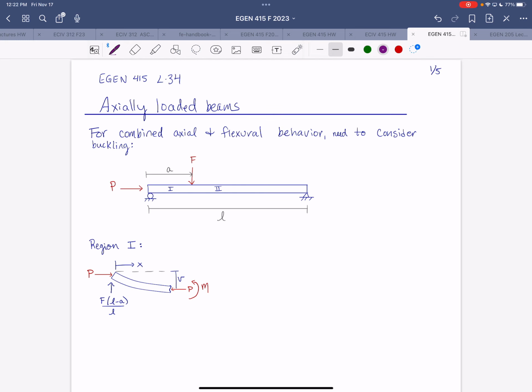Normally with beams and other structures, we proceed with the elastic analysis by neglecting the deflected shape that results from the applied loads, as far as how it changes the geometry and equilibrium. But for the case of buckling, we can't do that, so we use the deformed geometry to develop our solution for buckled shapes.